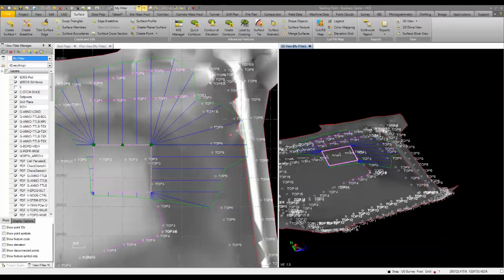So if we look here, we can see we're 3:1, we're shooting way out here, and we know that, hey, maybe that's too much. We want to bring this area back. We're good up here, maybe at 3:1, we're going to leave it that way. So what we want to do is go from a 2:1 slope to a 3:1 slope from this upper corner over here.